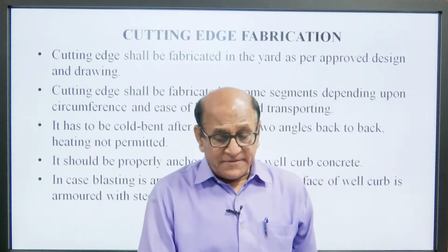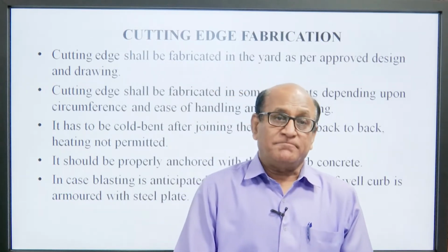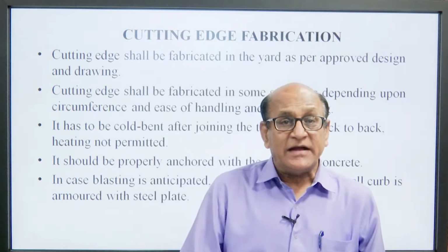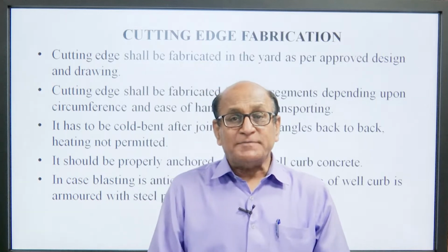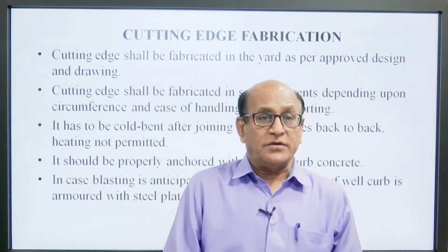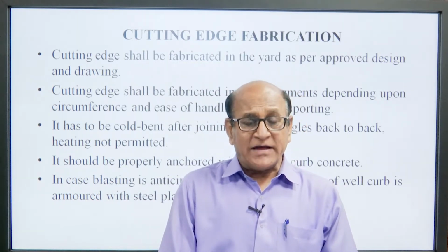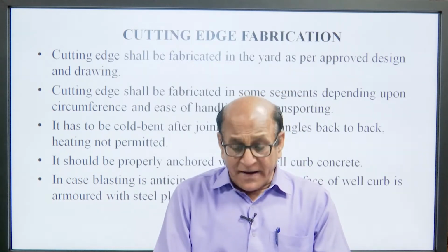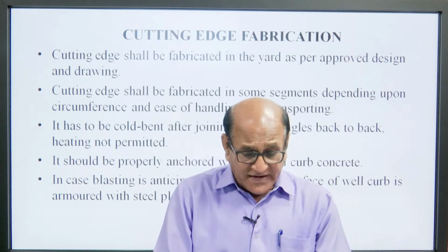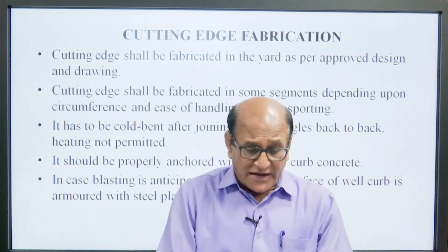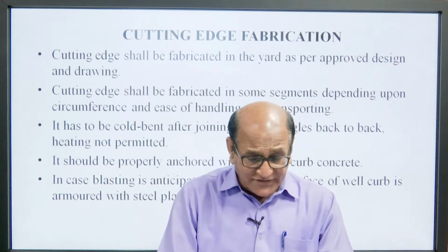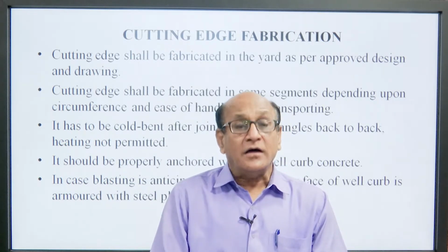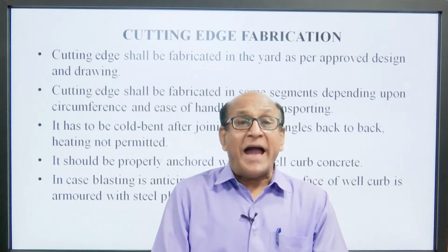The next is cutting edge fabrication. Cutting edge shall be fabricated in the yard as per approved design and drawing. It shall be fabricated in segments depending upon circumference and ease of handling and transporting. It has to be cold bent after joining the two angles back to back.